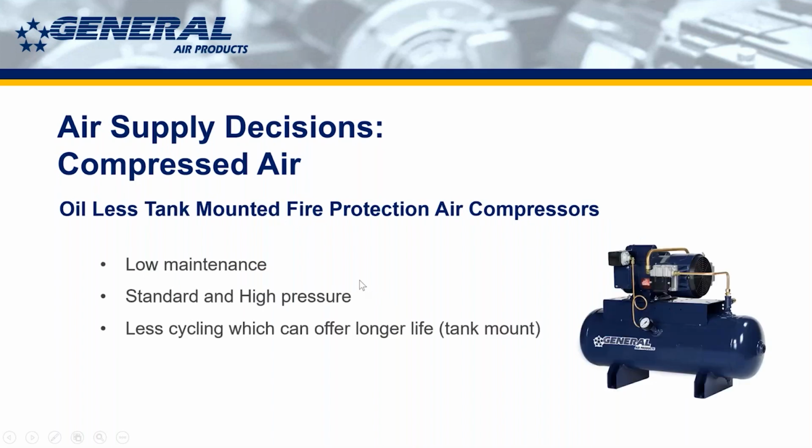All right, this is the tank mounted version of the oilless compressor. And again, tank mount is always the way that I would recommend to go over riser mount, even though riser mount is by far the more popular. Any tank mount, whether it's lubricated or oilless, is going to have an air maintenance device with it, right? If you have one system, you're going to have one air maintenance device. If you have three systems, you're going to have three air maintenance devices.